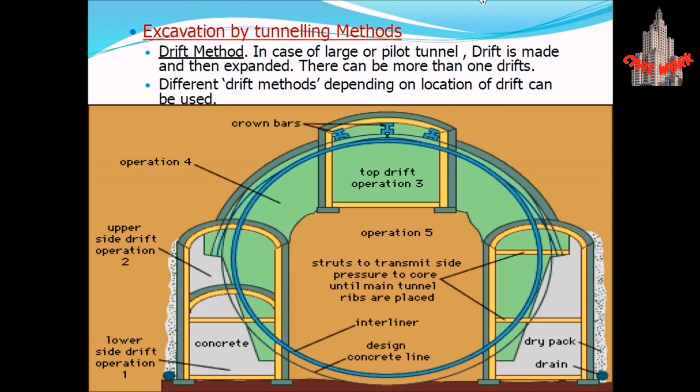Now the third method we have is the drift method. In case of a large or pilot tunnel, a drift is made and then expanded. There can be more than one drift. Different drift methods depending on the location of the drift can be used.